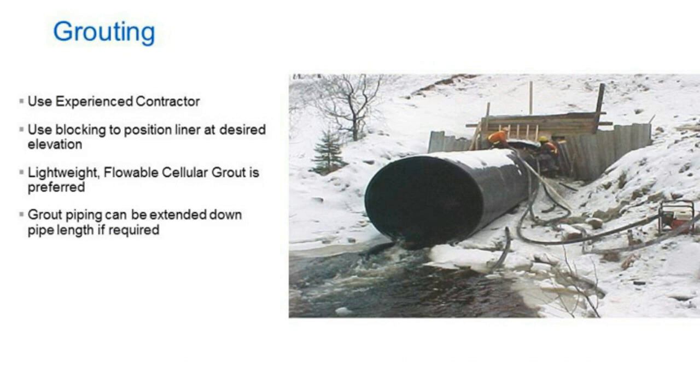Grouting is probably one of the most important steps of the reline process. This needs to be done for the entire length. This will ensure a good composite rehabilitation between the host pipe that's effectively going to carry the traffic for years to come throughout this rehabilitation of this culvert. So we want to make sure that the contractor is either an experienced grouting contractor as well as installer, or that he subcontracts this out to a contractor that may specialize in grouting.